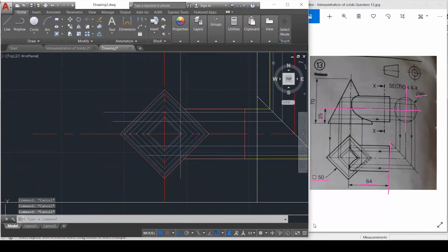And let me just go over here and annotate what I'm doing so that you guys following will understand what's going on. So this is my top point here. I'm going to project that to there, because we know that's the top point. Then I'm going to go down perpendicular to where this top point touches the center line, and then I'm going to make a point down there. What am I also going to do with the bottom, which is the lowest point? I'm going to put that in green, so that you guys could see. The lowest point is in green and the highest point is in red.